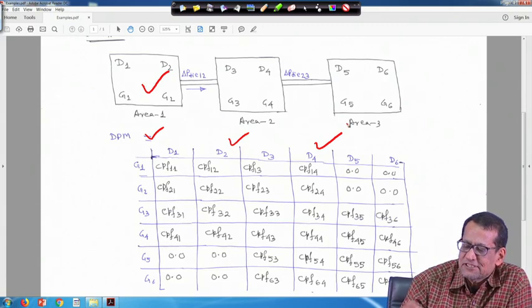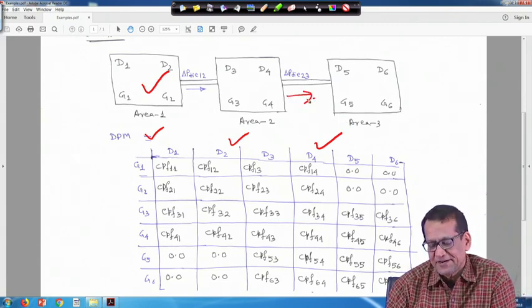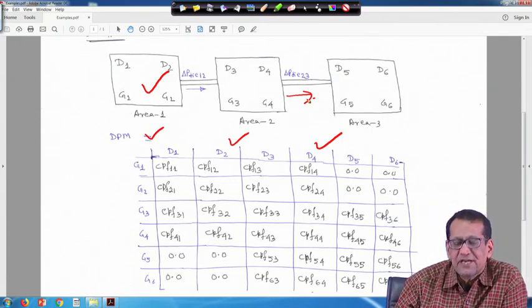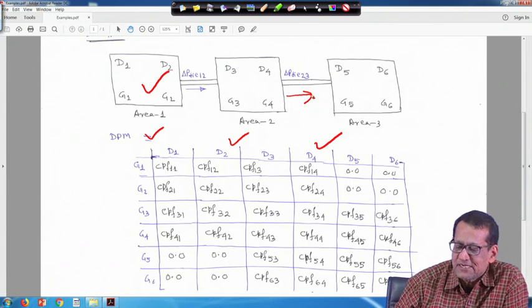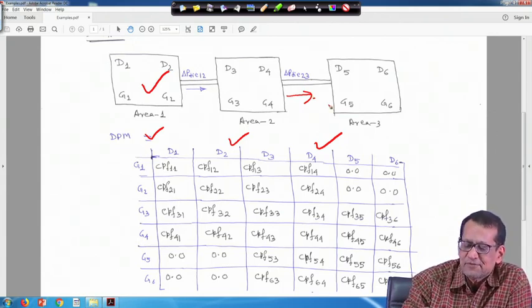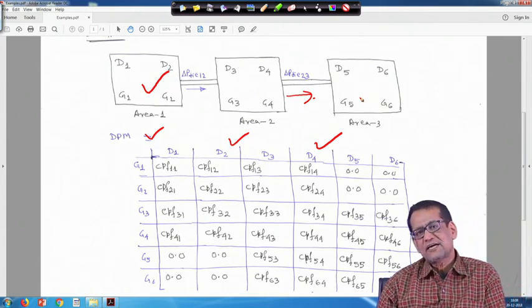And this is 1, 2, 3, and here also power flow is there, say 2 to 3, right. So, in this case this is delta P tie 1 2, and this is delta P tie 2 3. So, first is how to form the DISCO participation matrix. First you will look that it is a longitudinal system, 1 is connected to 2, 2 is connected to 3, but 1 is actually not connected to 3.